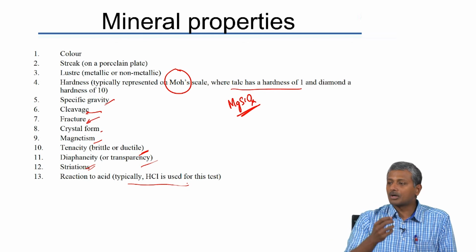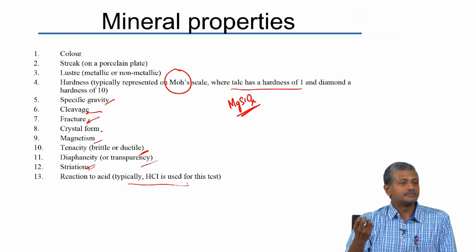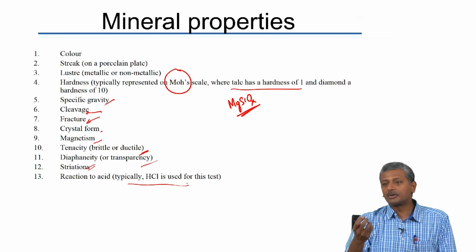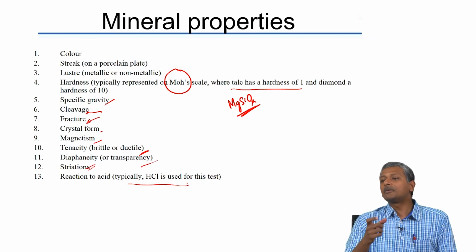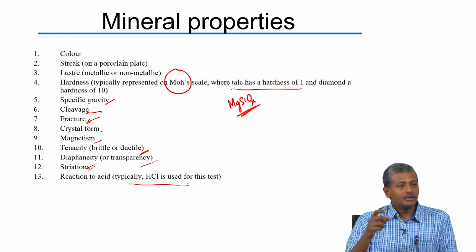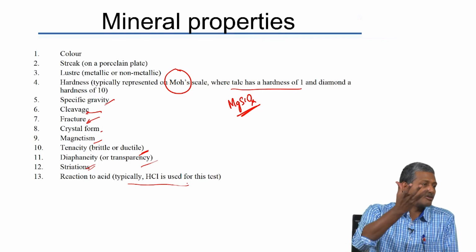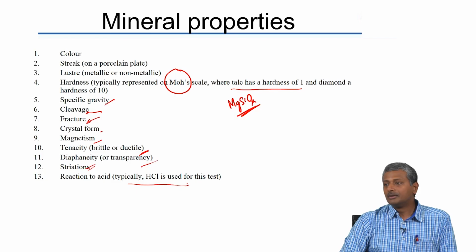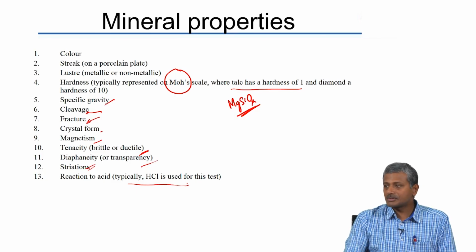So, when you drop the acid, what will happen on the aggregate surface? You will see bubbles coming out. What are those bubbles? CO2. So, obviously those are only there for carbonate aggregates. The limestone and dolomite, if you sprinkle acid on it, you will effervesce carbon dioxide. Granitic or siliceous aggregate will not have the same effect. Okay, so that is one test that is effectively used to distinguish carbonate aggregates from the others.